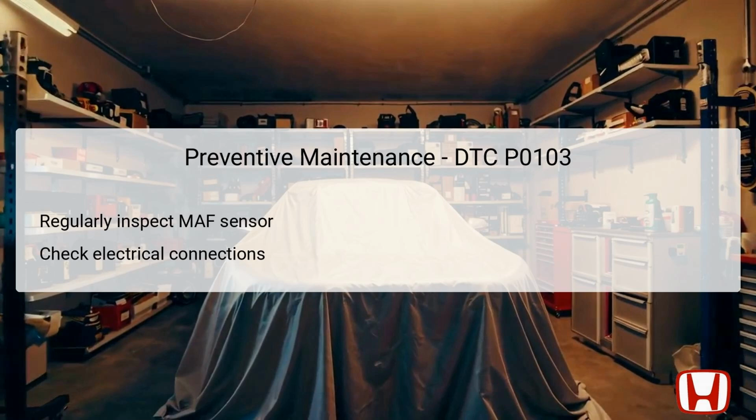Furthermore, routinely check all electrical connections related to the MAF sensor and PCM. This includes inspecting for loose terminals, corrosion, or signs of wear that could compromise the circuit. Making sure connections are clean and secure can prevent many of the issues encountered in MAF sensor circuits. Finally, adhering to regular vehicle service intervals as per manufacturer recommendations will contribute to overall vehicle reliability.